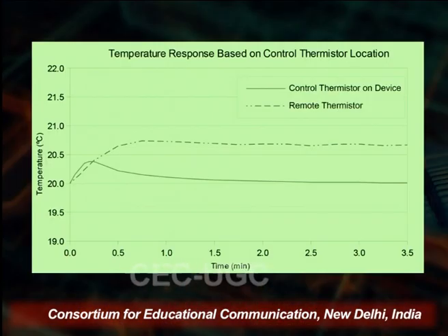On the screen here, we have taken from the literature how both thermistors work, the remote and the one connected to the devices. The response time of the connected thermistor is better compared to that of the remote thermistor. Once the placement of the sensor has been chosen, the rest of the system needs to be configured. This includes determining the base thermistor resistance, the bias current for the sensor, and the set point temperature of the load on the temperature controller we can measure.